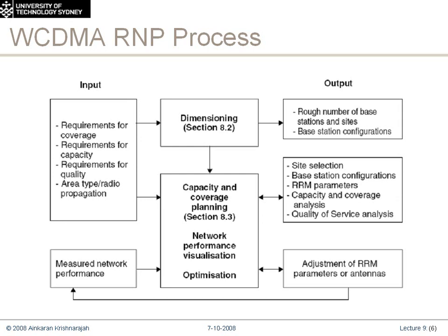The output at the end of the day is the number of base stations, where they are located, and general high-level parameters on how each base station should be configured. What power level should be output, what should be assumed for the mobile phone, and so on. So together the whole system should really work. And this is what a radio frequency engineer does on a daily basis, this type of planning.